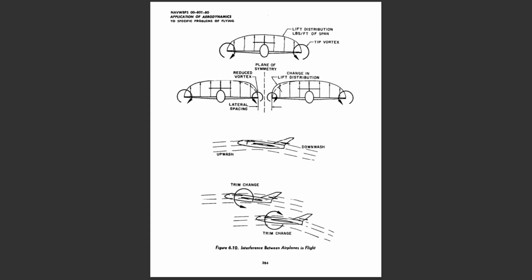In crossing under another airplane, care must be taken to anticipate the trim change, and adequate clearance must be maintained, otherwise a collision may result. The pilot of the leading aircraft will know of the presence of the trailing airplane by the trim change experienced. Obviously, some anticipation is necessary, and adequate separation is necessary to prevent a disturbing magnitude of the trim change.